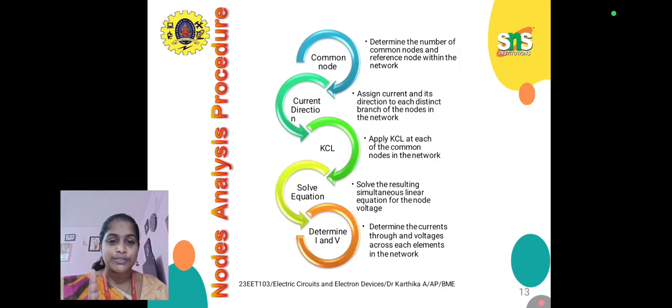Node analysis procedure. First is determine common node. Second is current direction. Third is KCL. Fourth is solve equation. And fifth is determine I and V.